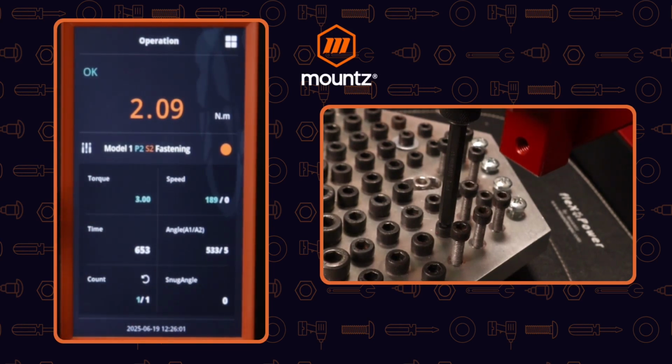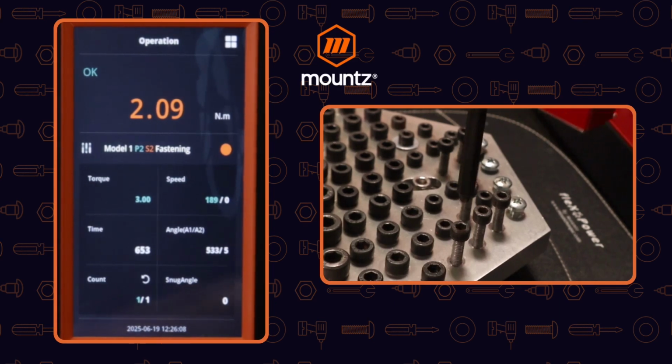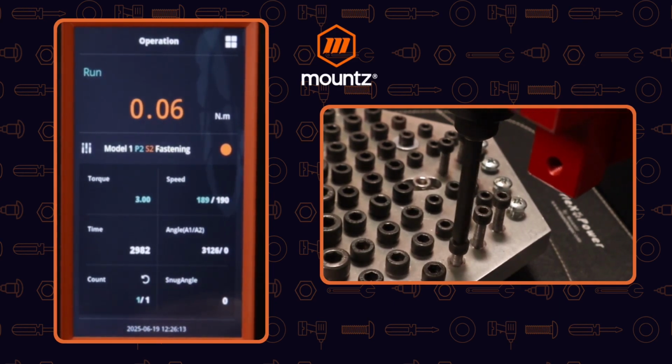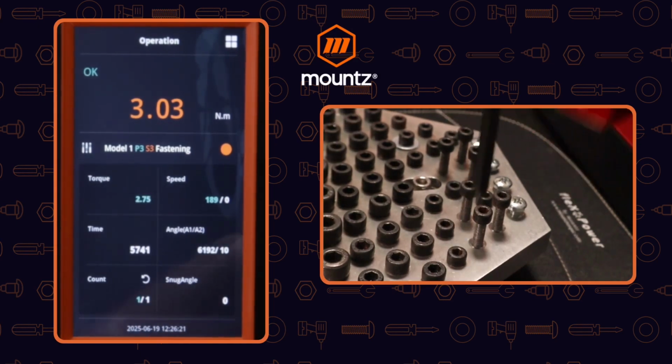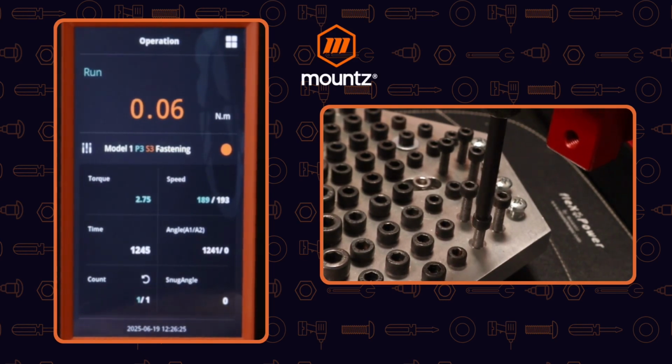So we've now moved to our second step, which is our fastening step, and has now changed our torque and our RPM for our next fastening location. And again, I don't have the free speed and free RPM for these other fasteners, but now we have changed again to our next preset.